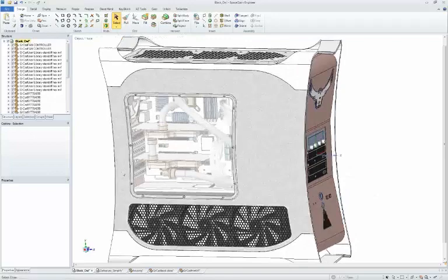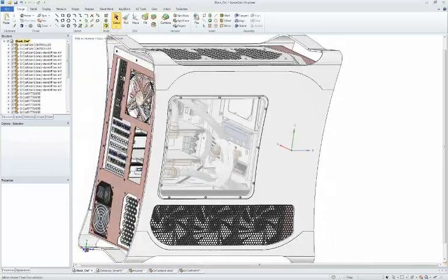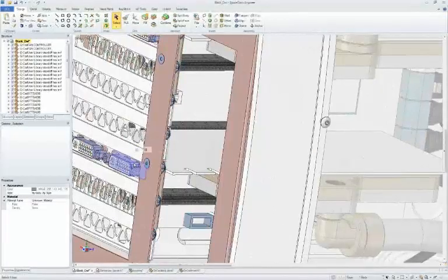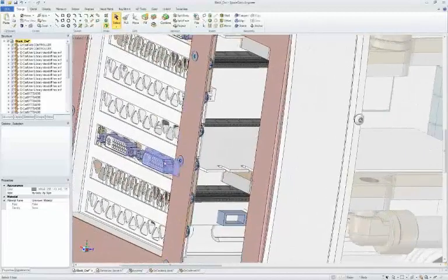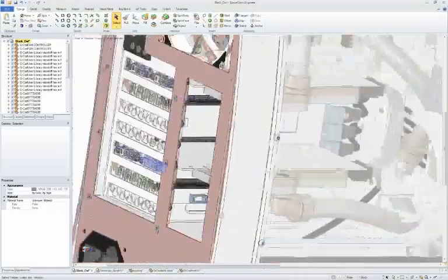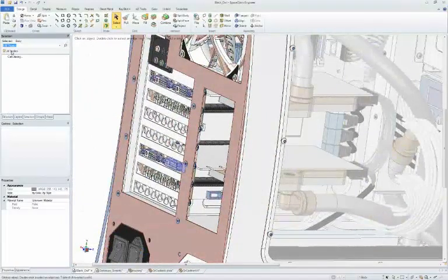But the last thing I might want to do in a design like this is start to get rid of small parts. Because again, there's about 750 parts in this model. What I'll typically do is I'll select something where I probably don't want anything this size or smaller. Just ballparking it for now. That handy selection tool, which speeds up the elimination of things, also works for bodies.